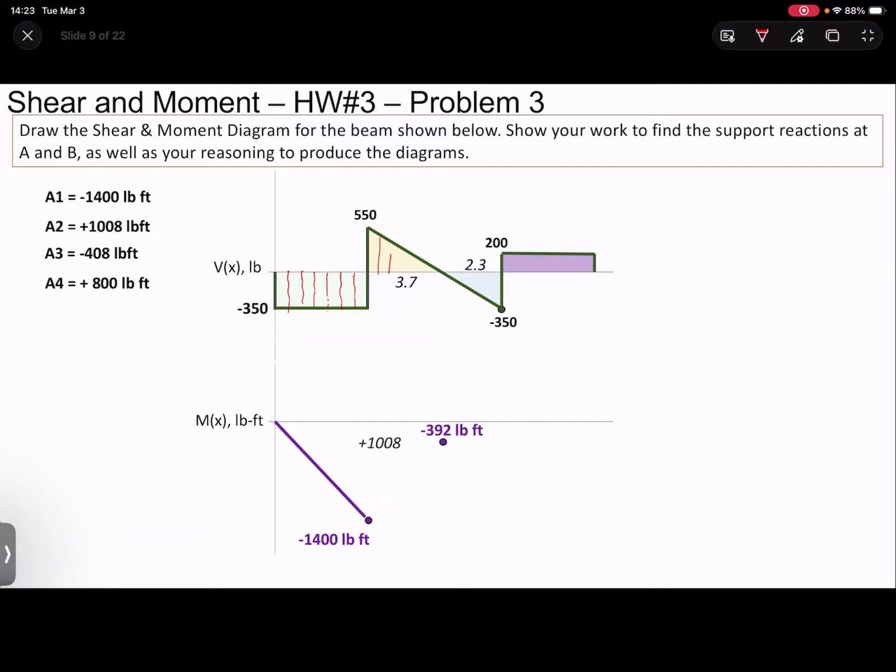And if we think about as we're adding these here, what is happening with the area as we are going from left to right in our triangle? The area is getting larger or smaller? Yeah, the area is getting smaller, which means we're adding less to our total moment. So that means the function is going to start really fast because we're adding a lot and then slow down because we're adding less at the end. So we have this concave or convex, gosh, I can never remember, convex like hill shape.